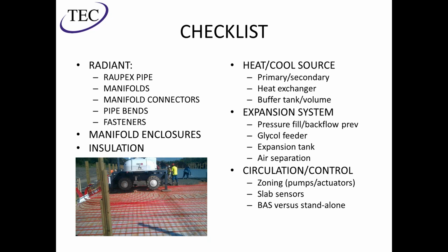But we definitely have manifold cabinets available if you want them to stand off of the wall or depending on where they're located. You want to make sure you or the concrete contractor are figuring for the insulation. Make sure you've addressed your heating and cooling source. If you got a lot of small zones, you may want to consider a buffer tank. But when you get into the more complicated jobs with lots of tiny small zones or larger areas, I would definitely consider getting the vendor involved or your supplier to help you break down what exactly you might need and if a buffer tank seems like a good idea there.